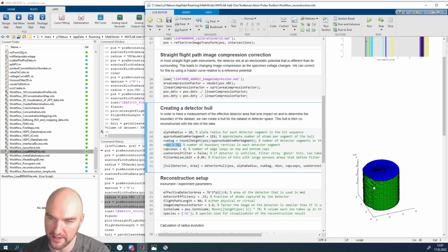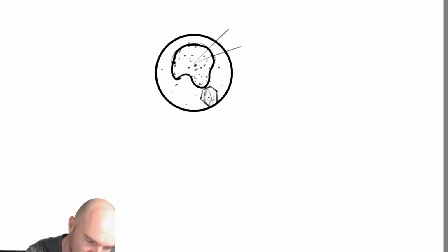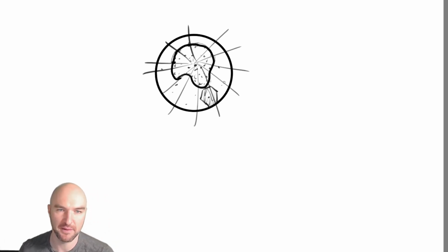What we're also doing is some nice remeshing. Our 2D alpha hull, just like our 3D alpha hull, is going to be something where the individual line segments are very arbitrary. So what we are doing is dividing it up into regularly spaced segments, into a regularly spaced n-gon, and I've set it to 32 lines for each segment. You can set it to 64, or you can set it to 16. But 32 usually gives you a pretty good outline. If you have some concavity in there, you might need to crank that up.